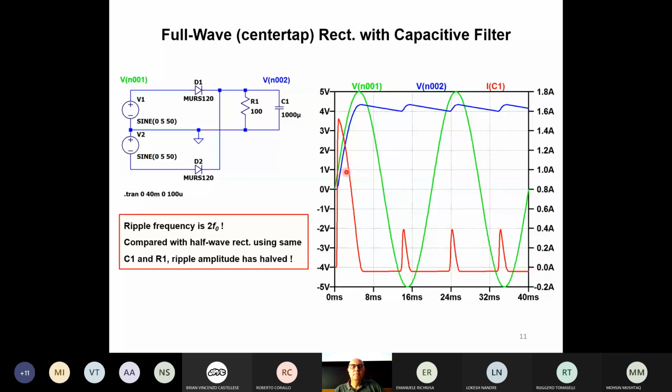What we see is that the capacitor, and so also the resistor, has a voltage which is more or less following the input voltage. At the beginning the capacitor is discharged, so it starts charging, then goes up to here. We have a peak voltage which is about 5 minus V gamma, so it's 4.3, 4.4. But then when the input voltage goes down, the diode opens, and so the capacitor cannot follow the input green voltage anymore. The capacitor starts to discharge across the resistor here.